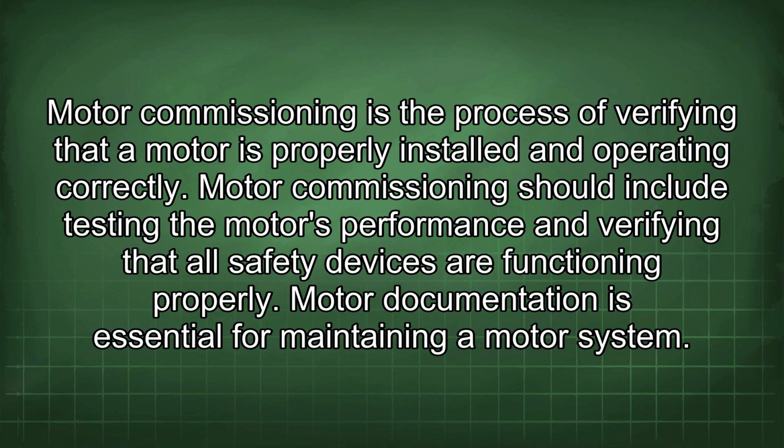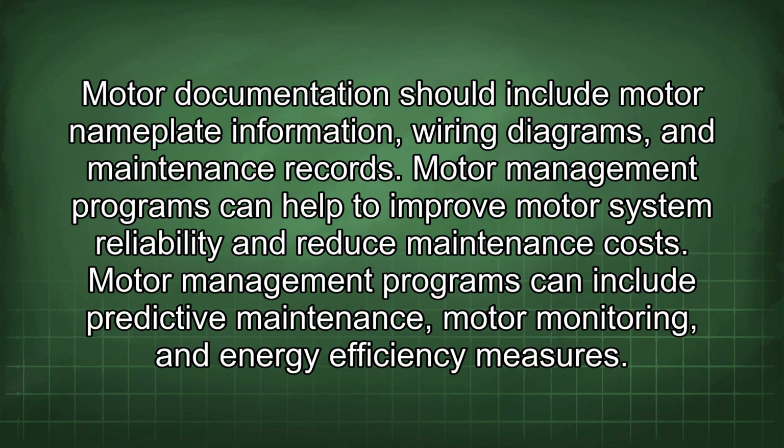Motor documentation is essential for maintaining a motor system. Motor documentation should include motor nameplate information, wiring diagrams, and maintenance records. Motor management programs can help to improve motor system reliability and reduce maintenance costs.